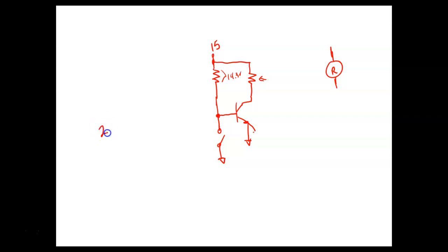So if you've got a 24 volt relay rated at, let's say, 100 milliamps, then all we need to do is make sure we have 24 volts up here, right? And so we wouldn't necessarily have to have a drop-in resistance. But if all I had was 24 volts and I had a 12 volt relay, then you could put a drop-in resistor in there, right? Does that make sense?